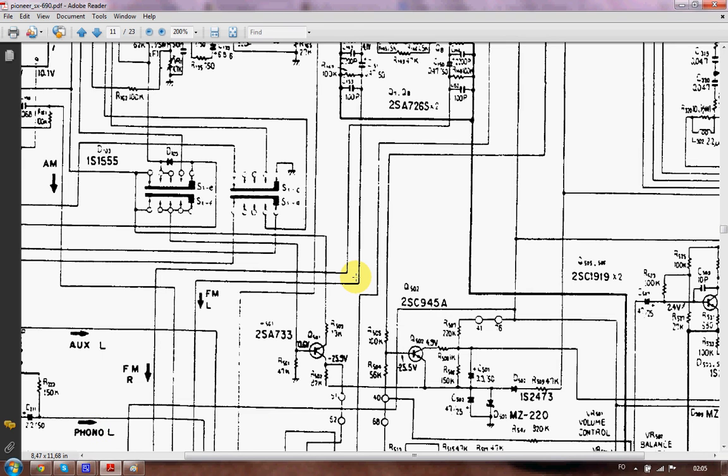So where do the signals disappear? And do an evaluation first. Is it only the radio which is defective? Does the auxiliary and phono work fine, but only the radio is defective? Or does nothing work? Or does only one channel work and one doesn't? If one channel works and one doesn't, in all applications, that means AM, FM, auxiliary input, phonograph, video, guitar, whatsoever, whatever you choose, there's always going to be one dead channel.